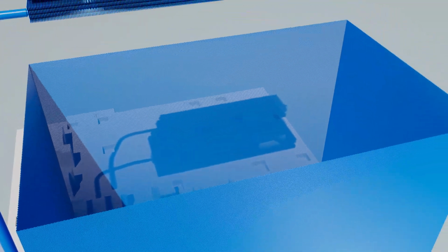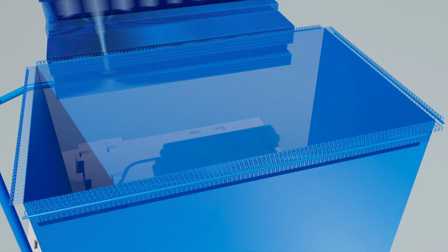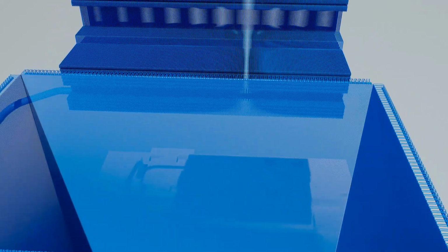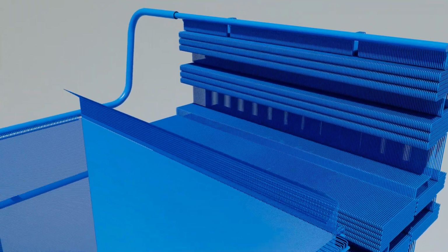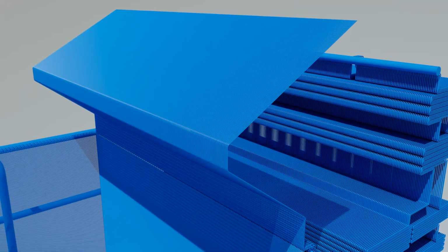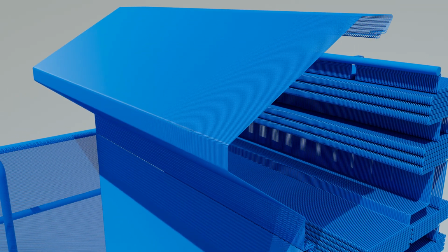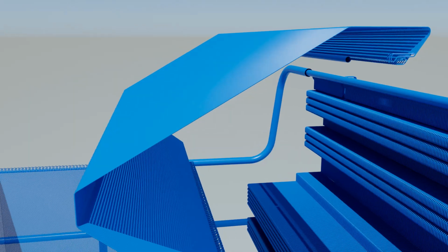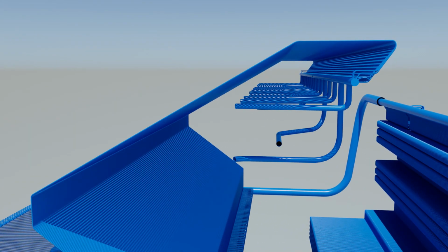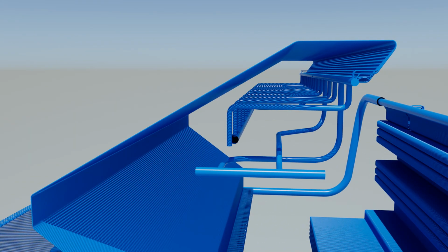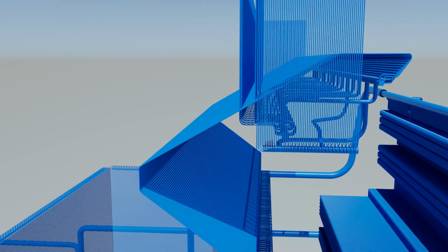The lower furnace path has a construction of the helical tube wall. The helical tube wall is introduced in the high heat flux zone around the burner. This zone shall have the two-phase flow, mixture of water and steam, at subcritical pressure operation during startup and low load in the variable pressure operation.